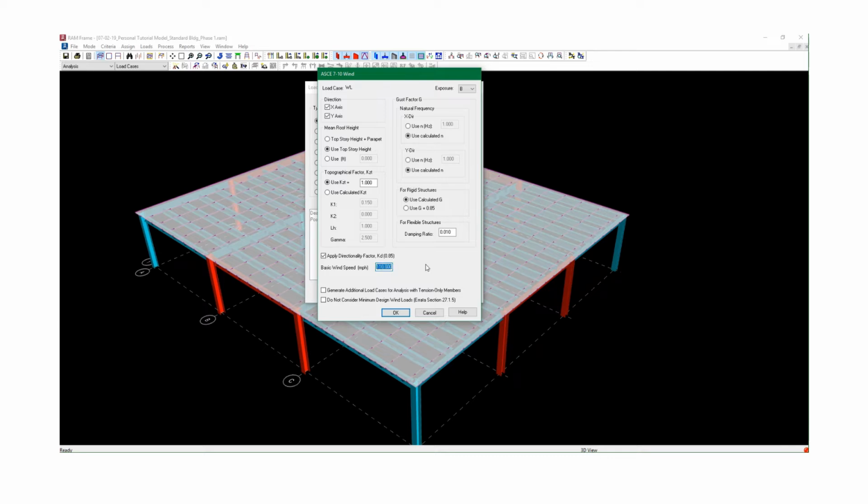But I think the value that we use in South Florida, again, this wind speed, this is an ultimate wind speed. I think the value for ultimate wind speed in South Florida is up to like 150 or something. In hurricane zones, that's what you might use, 150. If you're in the mid-Atlantic area, Maryland, DC, and Virginia, this value is actually 115. Some jurisdictions, some building departments or agencies might use 120 for this value. This is the ultimate value.